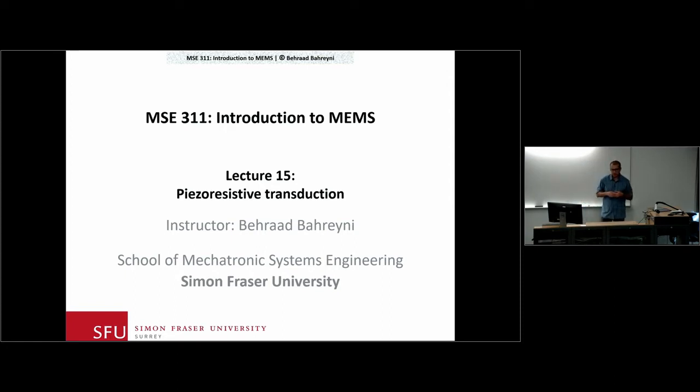So what we're going to do in the next few lectures is talk about the transduction mechanisms that are important to us at microscales. A lot of these also have applications at larger scales. And today we start with probably the most familiar one, piezo-resistive sensing or transduction. And then we talk about piezoelectric, thermal, and electrostatic transduction as some of the more common transduction mechanisms at microscales, and also talk about a few other ones that are not as common but have their own place in the industry and in the field.